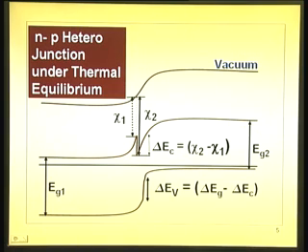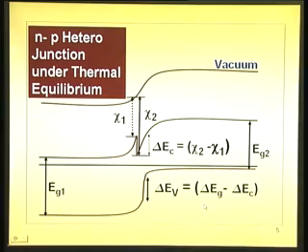Now, what we said last time is you have this notch, delta E c, or discontinuity in the conduction band, given by chi 2 minus chi 1. We have derived that. That is called Anderson's model, the first model to understand. And delta E v will be equal to whatever delta E g is there minus delta E c, or delta E v plus delta E c is the delta E g. Okay, I think that is clear enough.